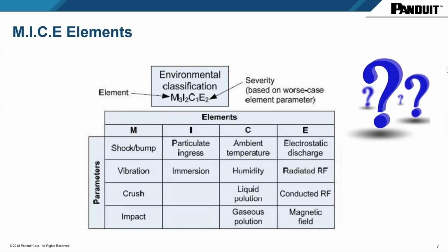So there is radiated RF signals that come out of these power systems that cannot be helped. And we need to be very cognizant of these RF signals and other emissions that come out of the power systems that affect the communications. You will find those issues around drives. You will find them around power cabinets. You find them in many places around the factory.